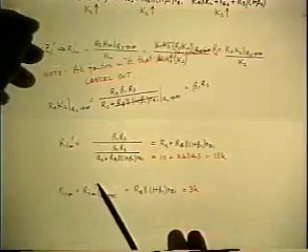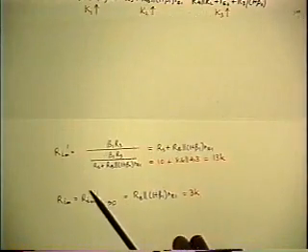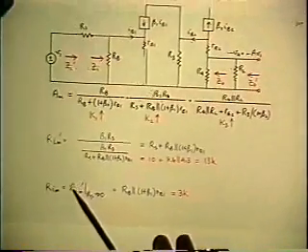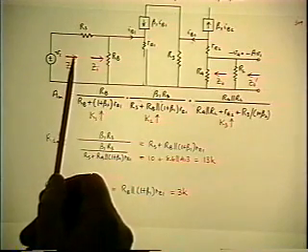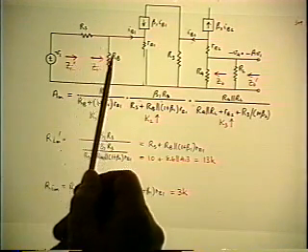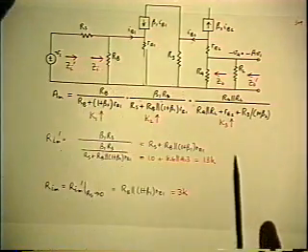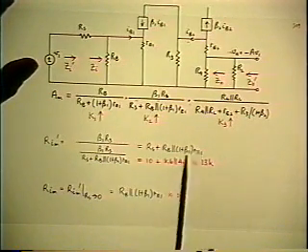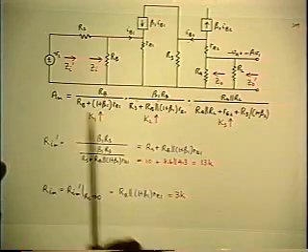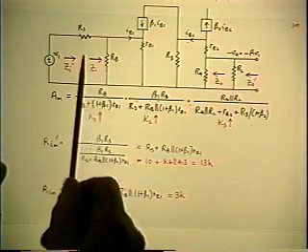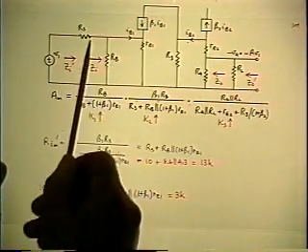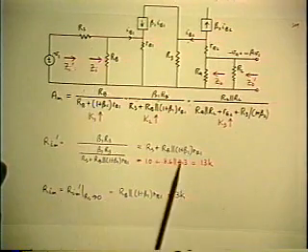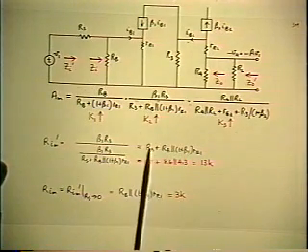And again, this is a simple enough case that the answer is obvious anyway. The outside input resistance is RS plus RB parallel the reflected RE1, which is exactly what you get out of the theorem. If you want the inside input resistance, you just let RS go to 0 in the previous answer, which of course simply takes away its additive effect.